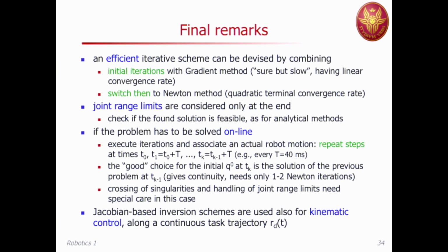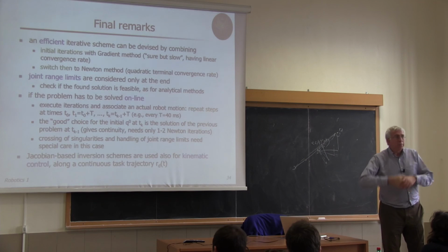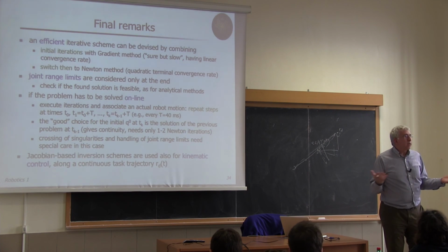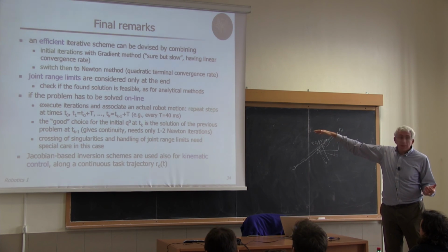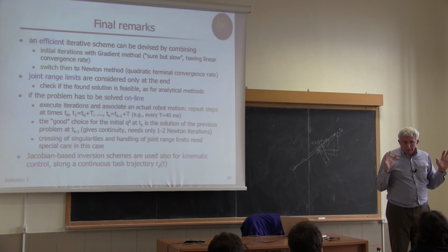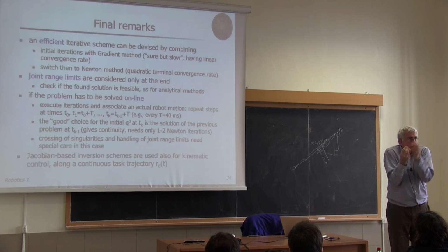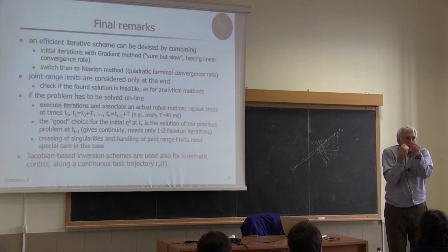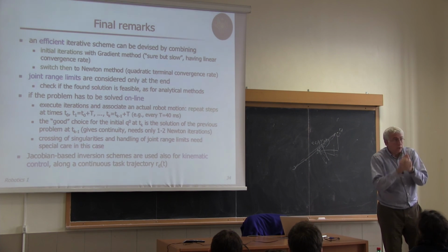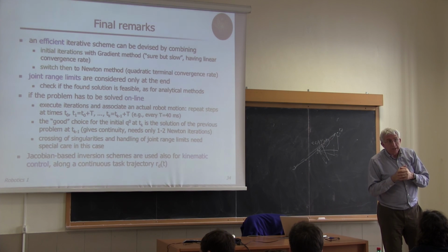And this is just a reminder. We will see that these Jacobian type methods, inverting the Jacobian, pseudo-inverting the Jacobian, we will encounter them again when we talk about control. And in fact, moving the inverse kinematics to an online version is almost control. It's almost feedback control, because I see an error, I'm in a good position. The desired pose changes, I see an error, I want to compensate for that. So I'm solving the new inverse kinematic problem.